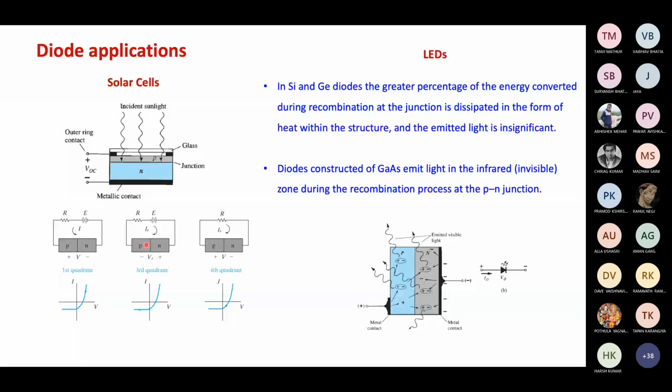Because now the electron hole pairs. So please remember that this is the characteristics in presence of light. Okay, and in presence of light, a large number of electrons and holes are being generated, and that increases this reverse current quite a lot actually. So now this current is no longer microamperes or so, it may be milliamperes as well, depending on the intensity of the light. Do you get it? Yes. And so, not the same IS that we had previously.